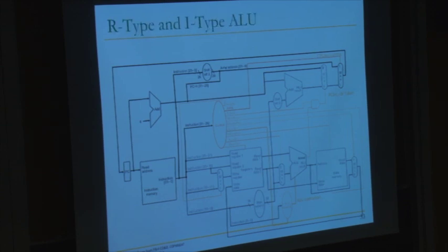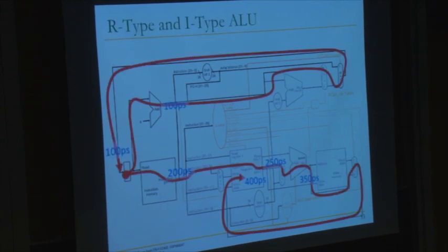But if you look at the R-type and I-type ALU operations, there are 2 things that happen concurrently in the single cycle microarchitecture for these instructions. One is the ALU operation itself, which does form the critical path. Well, I guess it's instruction fetch plus decode plus register file access plus ALU execute. You bypass memory, and then this is the 0 picosecond assumption, right, with the mux that we had. That's why you don't add some time. And then you write to the register file.